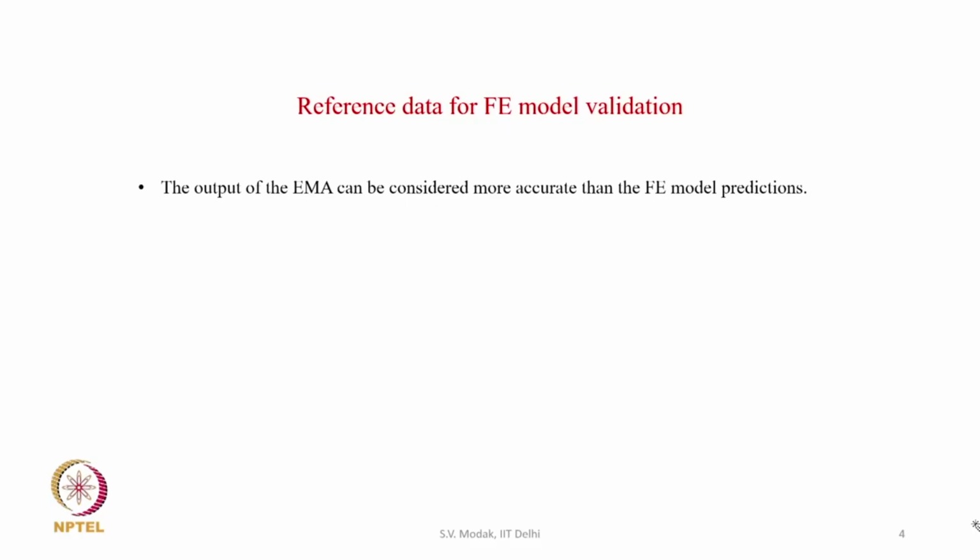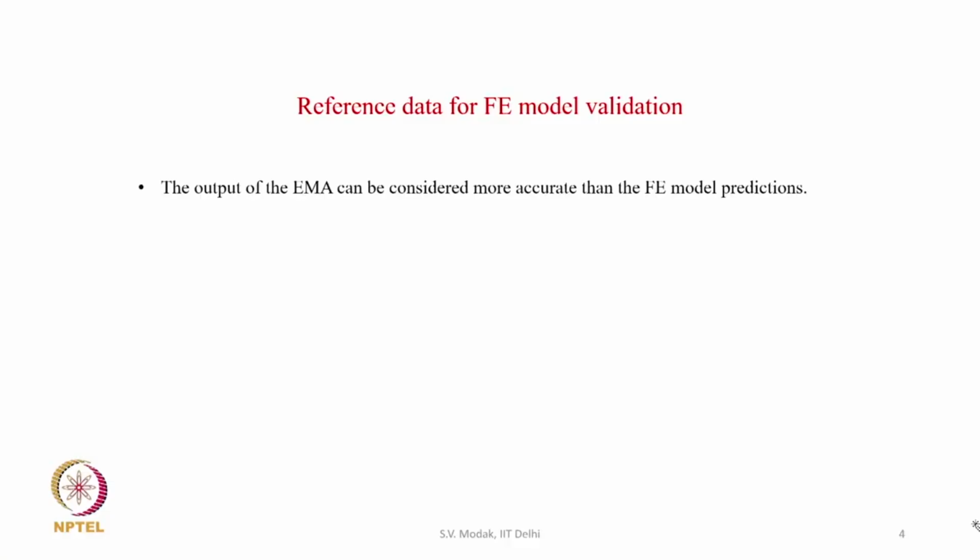One may say that there may be some noise that is generally associated with experimental data like a modal test. So, then how can that be considered as accurate? So, the point is that the modal test results we obtain from the experimental modal analysis are accurate, but they may be a little bit imprecise because of the noise that might be present. But this noise, which causes some variability of the measurement, is random in nature. So, that small variation from measurement to measurement is due to the random variation in the measurement, right. So, there is some random noise that may be associated, and this random noise can be reduced by the process of averaging. So, we can obtain an accurate estimate of the true characteristics by the process of averaging. So, therefore, the modal test data is accurate, though it may be a little bit imprecise.